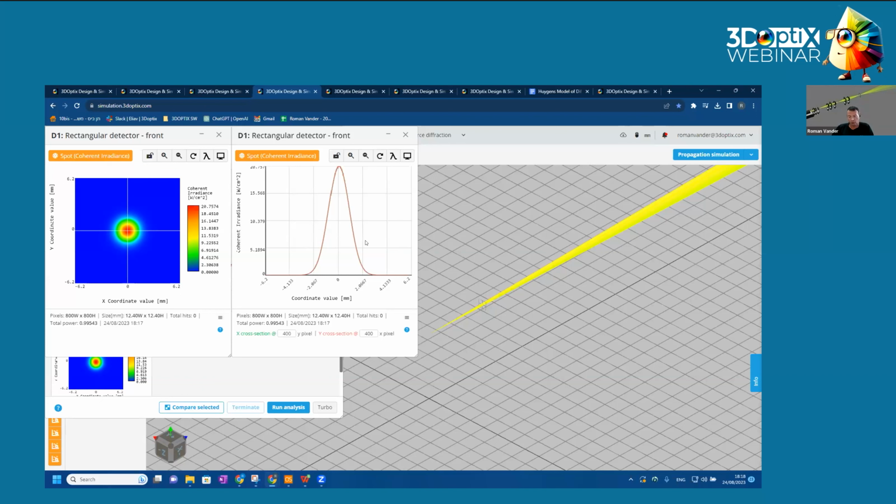And we do in parallel 2 additional processes. First of all, we would like to add Fresnel diffraction. Fresnel diffraction is much less accurate than Huygens, of course, but it's fast. It is limited to paraxial, and all the limitations, but it's fast because it's based on Fourier transform. So we will be releasing Fresnel, so you can play very fast to adjust your system, and then when you know that it's okay, you can run Huygens and get a very accurate response.